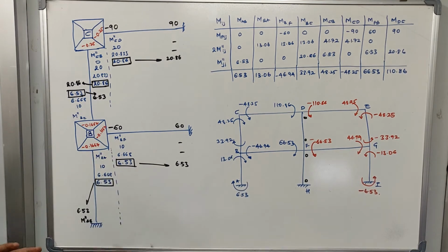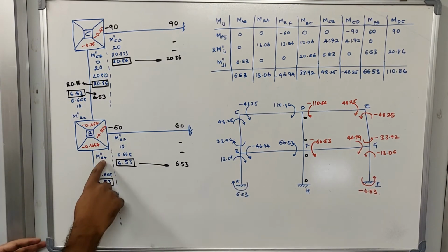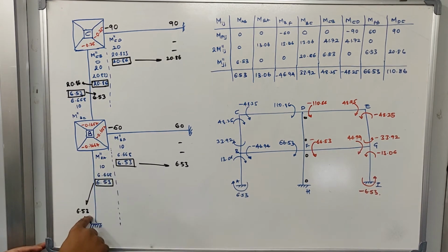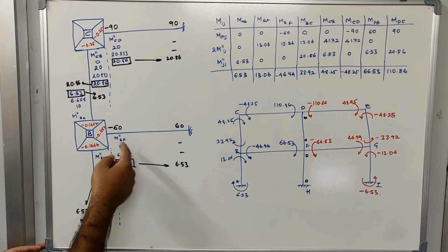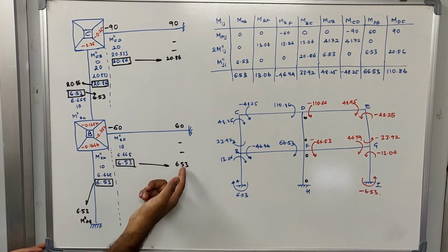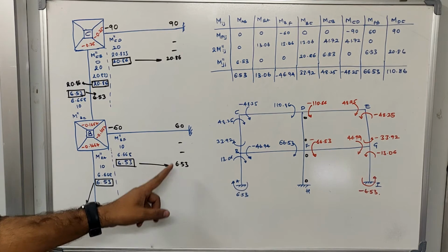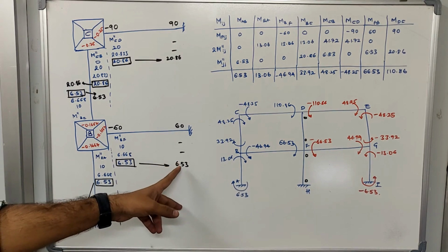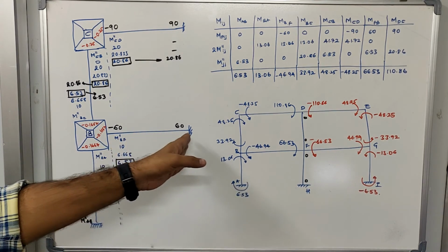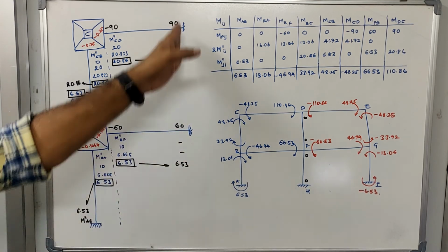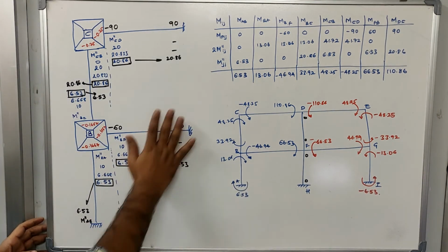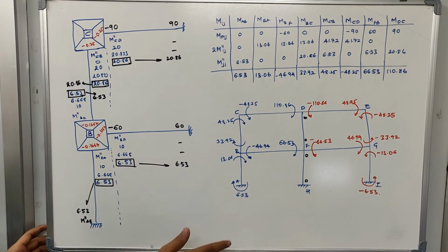So the next thing is to carry them over. For example, whatever rotation moment I calculated for BA should be carried over to AB. Whatever is calculated for BF is to be carried over to FB. Now see, in the previous problem we had not done this. In the previous problem we had not solved the moments at the section ends. If I had taken the section at this point, I had completely neglected this part, but here we are not going to do that.